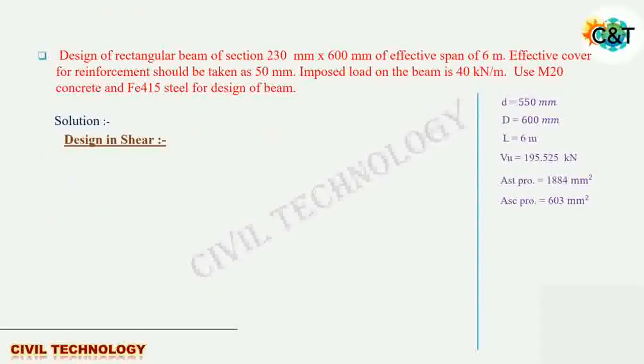So for shear, first of all we have to check whether the minimum reinforcement suggested by IS 456 is sufficient, or we have to provide some more reinforcement over it. For that there are a few factors we have to calculate. First is the design shear stress.